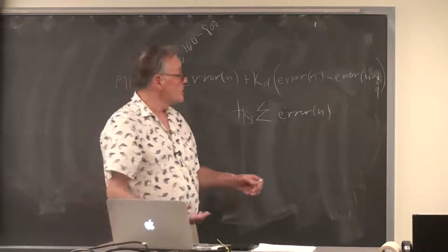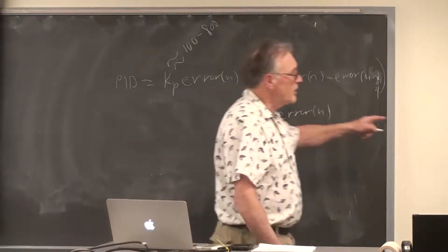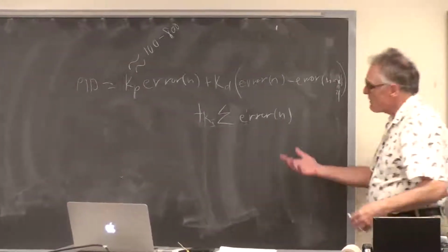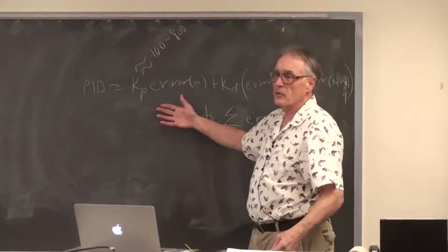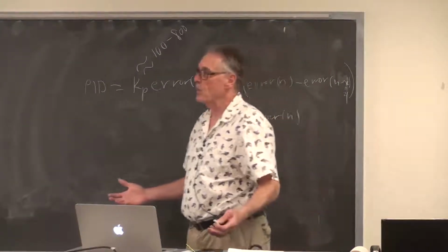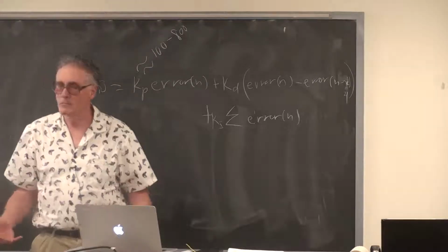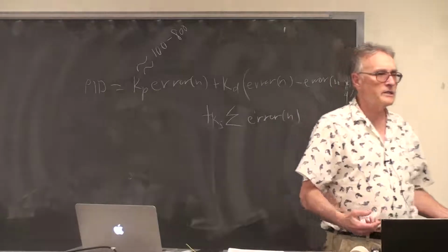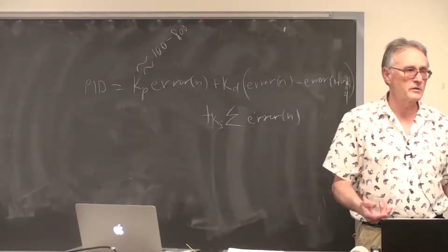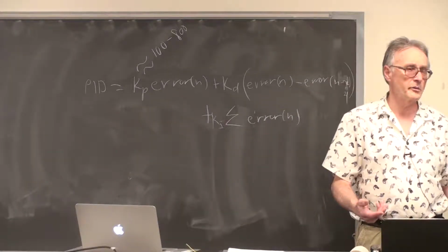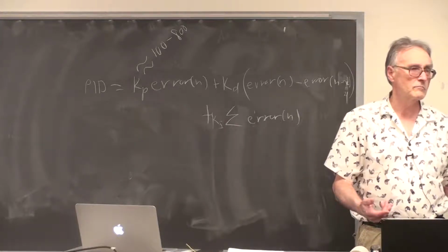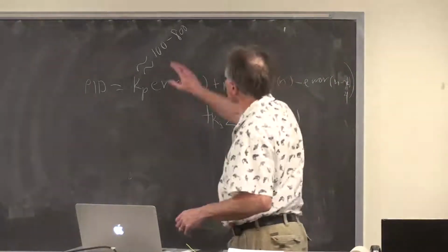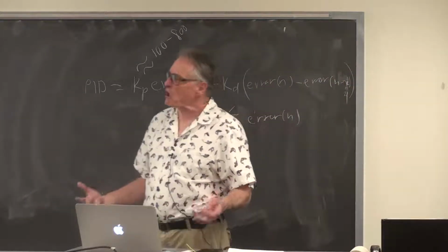Yeah. So if we have a large error, 250 units, and we multiply it by around 200, then we're going to get a number around 40,000. And so the motor is going to be at full power. So this suggests that a constant in the ones or tens is going to be too small, and in the 10,000s is going to be too big. So setting it to 100 might be a good place to start.